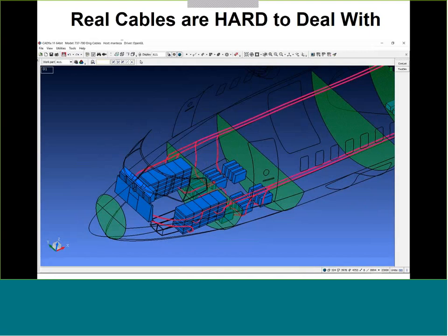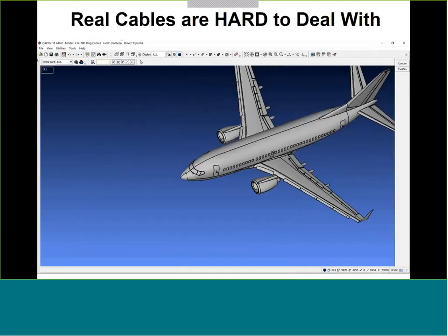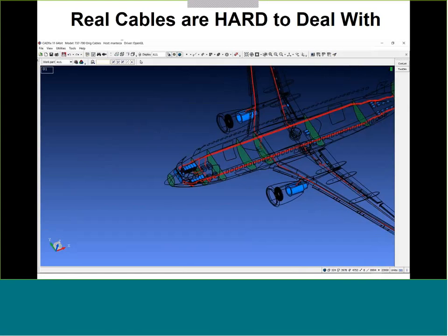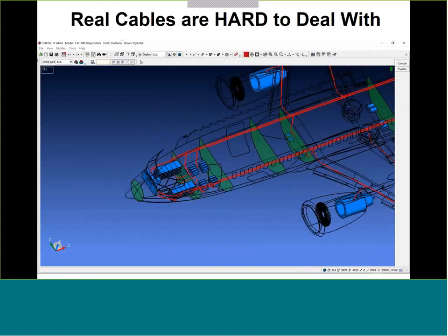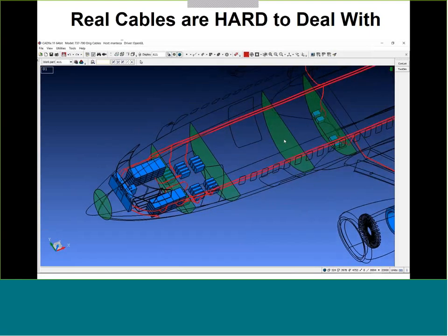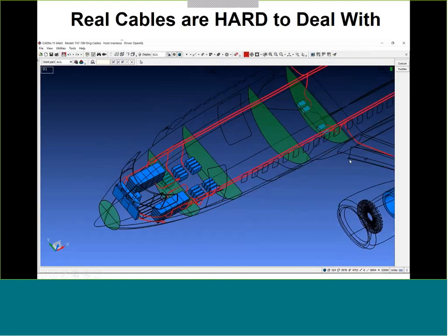There is not any simulation tool I know of that can handle the 3D drawings like this and know what to do with the pins inside, that can understand the individual shields and the interactions there and get the right answer. This is just not the right information. And further, all those details, these days, they don't actually exist in the CAD. So if you open up CATIA, you're going to see these bundles like this that represent the cable routes, but it doesn't necessarily know the cable wiring diagram.